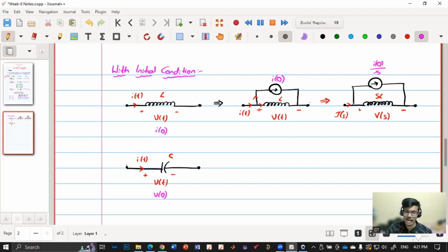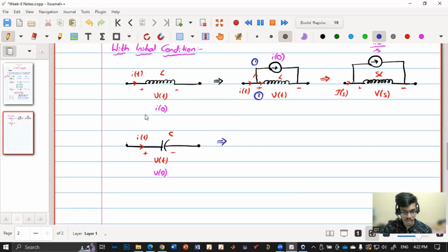When we are trying to add currents, the current will have a branch, another branch, because for current we'll apply nodal analysis. If you're dividing the current into two parts, then those two branches, this first branch and this second branch, will be in parallel, because only then will the currents be added. In the case of the capacitor, we are separating the voltages and adding the voltages. When you separate and add voltages, it will be series. So current, it will be parallel, whereas for voltage it will be series. I hope you understood the logic I'm trying to explain here.